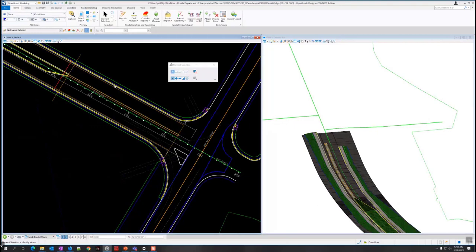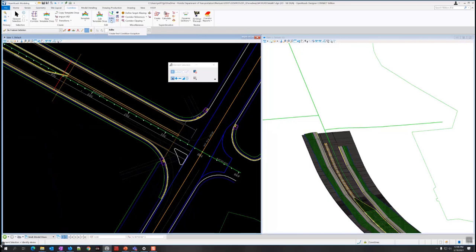That's better. Okay, now we go into exercise 2.10. Let's add these point controls. So we go to the corridors tab, and we want to go to the edits drop down. Click on the drop down because you don't know which command is going to use. The very last one is create point control. So select that, and then as you locate the corridor.